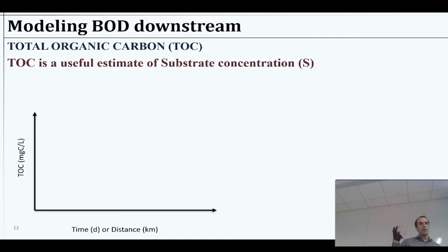Well, first you scrub it of any CO2 that's dissolved. So you acidify it, drive off all the CO2 you can. Then you take it and say, all right, well, now let's subject it to really, really harsh oxidizing conditions and measure CO2 over time, and you get a good approximation of all of the organic carbon in there. It's very similar to measuring chemical oxygen demand.